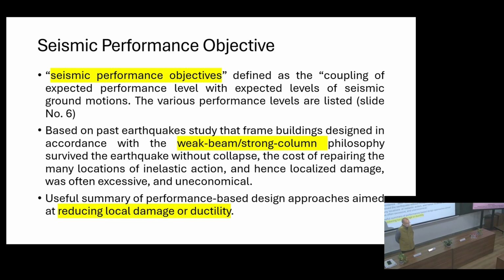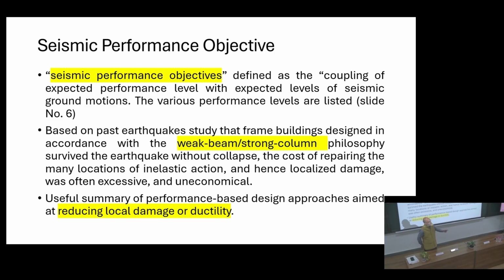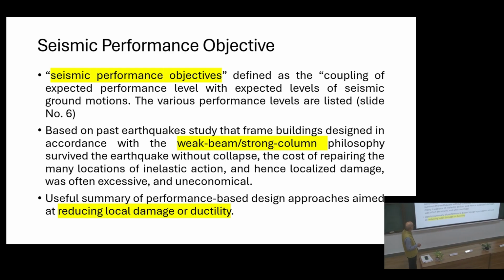So that is why the concept is, as far as possible, you design the structure so that the plastic hinge forms in the beam. That is precisely performance. So your design has to be such that, in other words, you are predefining where the damage is to take place in the structure. That is very important. So the localized damage will take place.